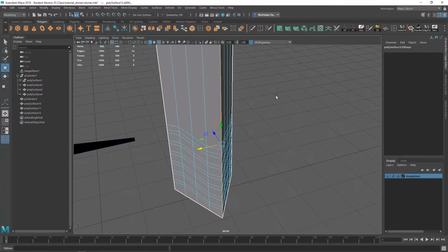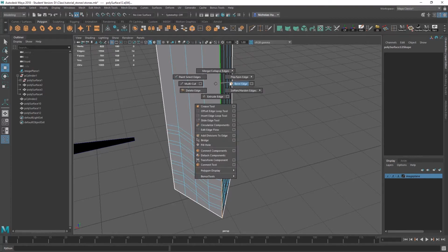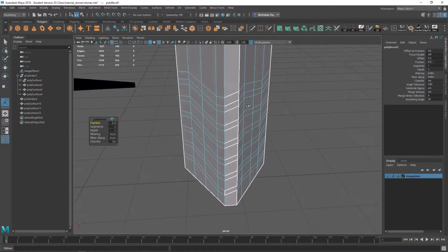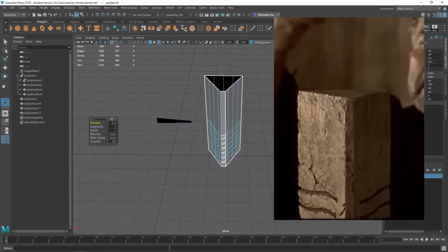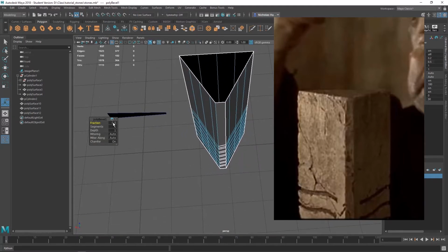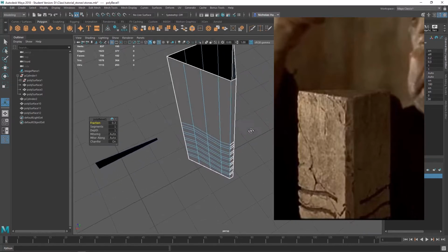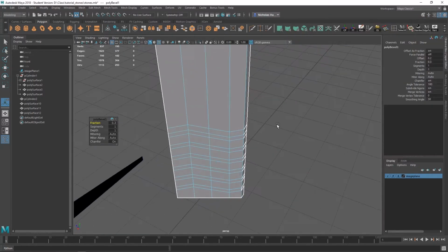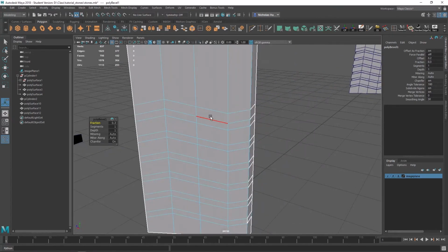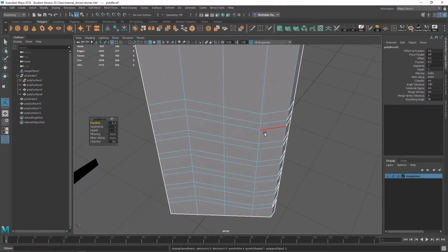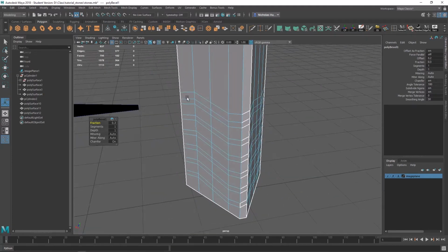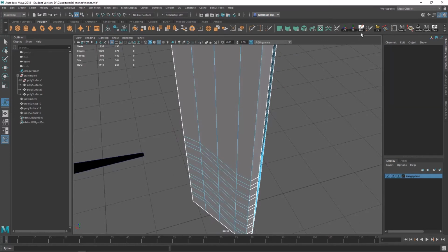Double click this edge, and I'm going to hit our bevel button that lives here, or you can do Shift, right click radial menu, bevel edge, and I'm going to eyeball it. It's probably a little bit sharper than that, so maybe 0.3. That looks about right. And then when we go into extrude inwards, I want to not, maybe I can show you that right now. Nah. We'll just extrude inwards and I'll show you how to control that shape in a minute. I'm going to delete history.